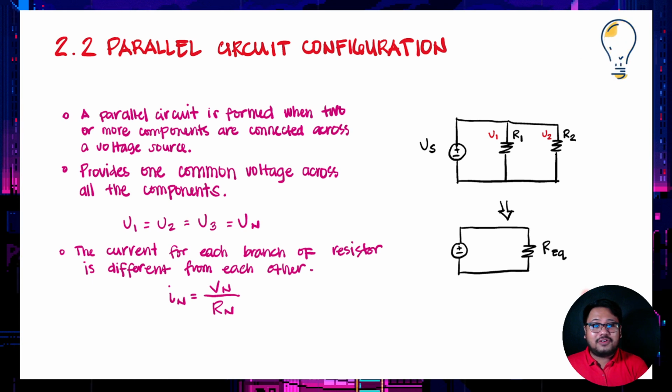Parallel circuit configurations are actually used to connect components that require the same amount of voltage. The most common application of a parallel configuration is typical house wiring to the power line. With many lines and appliances connected across the 220 volt source, the wall receptacle has a potential difference of 220 volts across each pair of terminals. Therefore, any appliance connected to these receptacles will always have 220 volts.